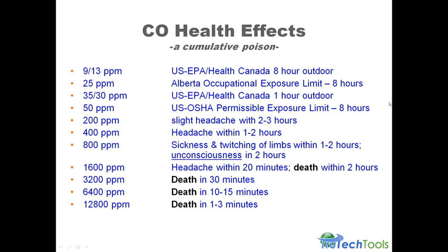If I've got a cup of water and I've got a gallon of water, and I put a drop of oil in each one, I have the same drop of oil in each reservoir, but they're two different sizes. The proportion is completely different. I have a gallon in one, I have a cup in the other. Both have the same drop. That drop represents the CO. That's what we're concerned with, because when the CO mixes with the ambient air, that same drop is going to end up in there no matter whether we have the gallon of excess air or the cup of excess air.